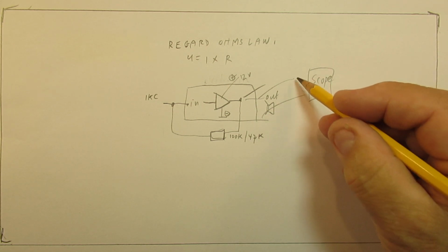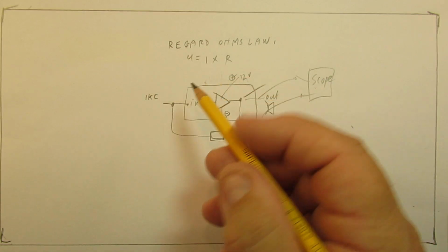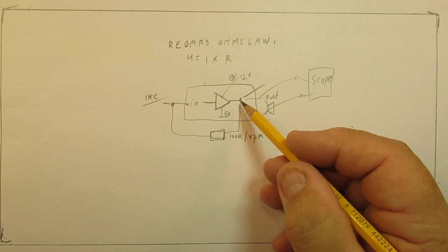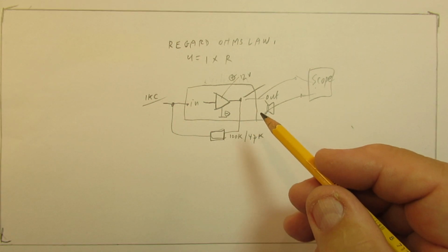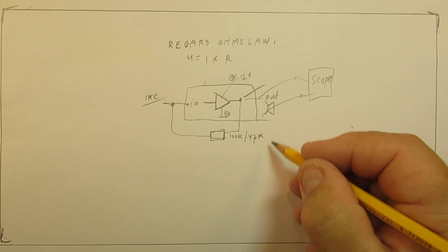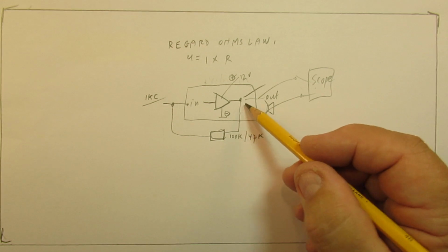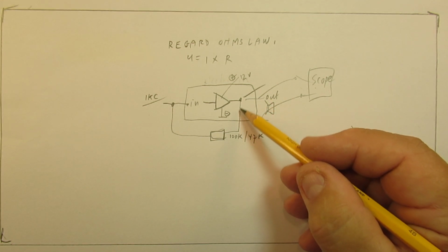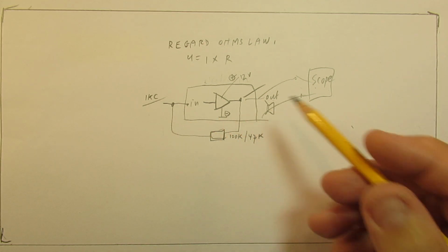Very important, always use your scope and see how that will work. Send in 1 kc and study how the effect will be. A resistor is not frequency dependent. That means that in such a case, in many circuits, you get a current flowing here, and there is no frequency dependency.